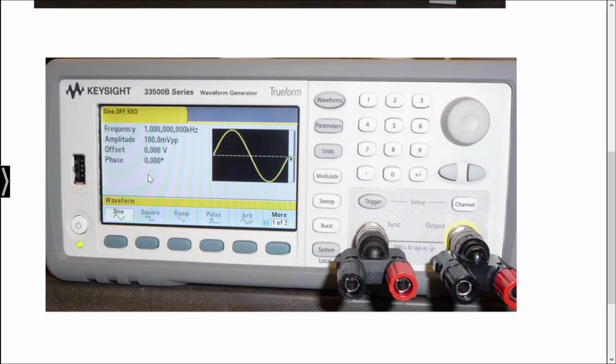First you can see, for example, what the amplitude is, basically the magnitude of the sine wave, what the frequency is, how many cycles do you see per second. That's what hertz is. So like 1 kilohertz is 1,000 cycles per second, or 1 millisecond per cycle, right? 1 millisecond is the period, which is the inverse of the frequency. So it's pretty easy to set these up, and you just push the button. The knob basically allows you to change the frequency. With a little bit of trial and error, I think you can get this to work pretty easily. And the output is taken from this right terminal.